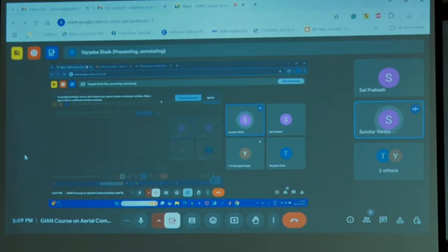The threshold is controlled by theta, which is an SNR threshold. Theta is related to the size of the packet. If the packet size is large, theta is large; if the packet size is small, theta is small. That is intuitive, correct? If I want to send a large packet, I need very good SNR, because if the packet has a problem anywhere, the entire packet is lost.